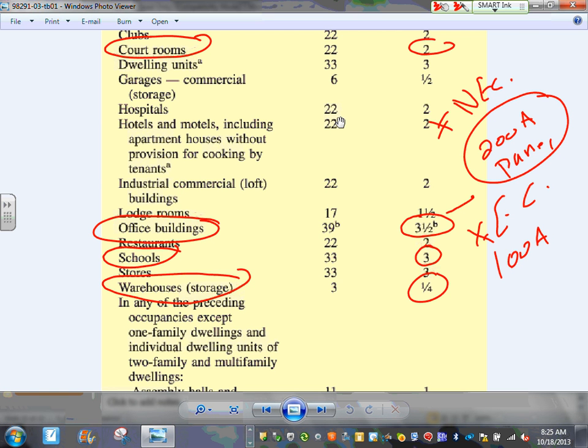In 2014, just coming, the 2014 NEC code book will allow you to use the 100 amp. So the NEC code book is catching up with the energy code. This is a major change, believe it or not. As engineers, we always use our judgment too, but now at least the NEC code book is acknowledging that judgment.